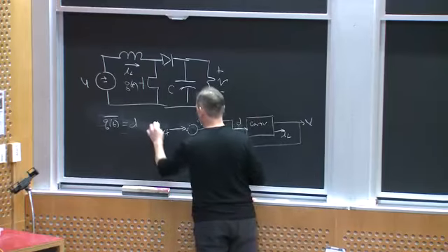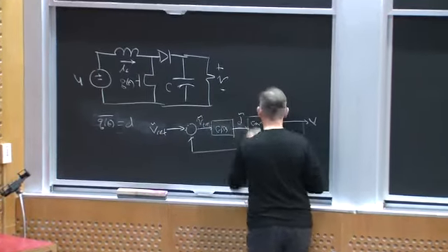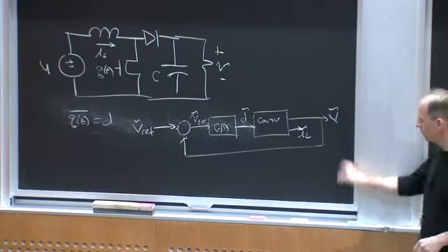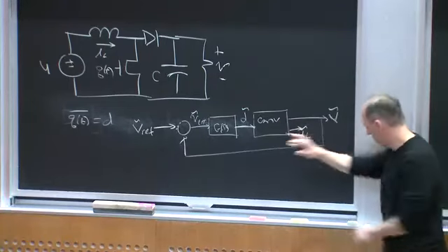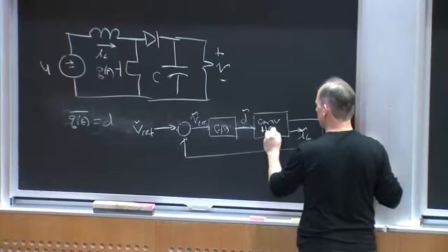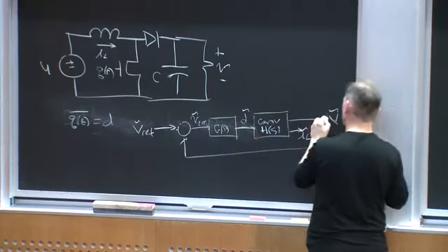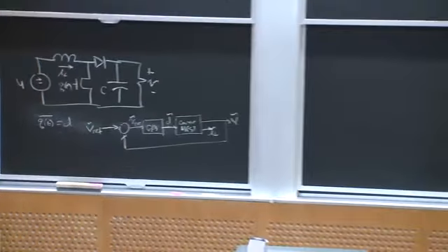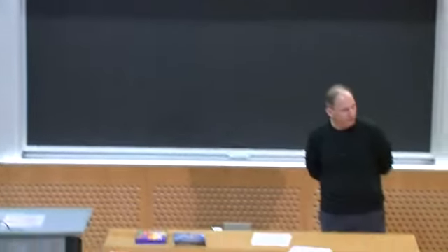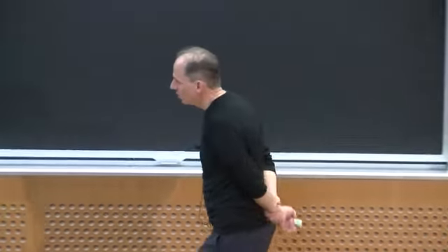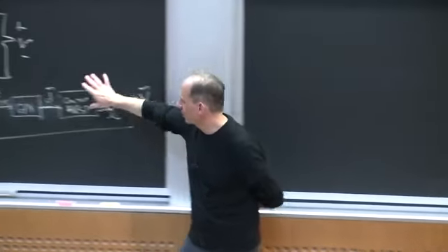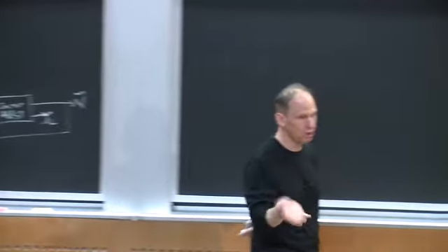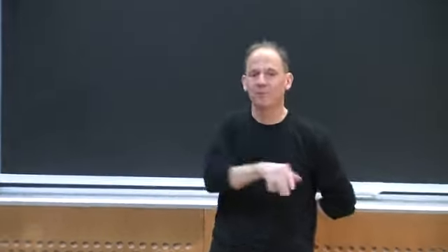So I might think about the variations in all these things to linearize it. And we came up with a model for our converter, H(s), which basically converts between variations in duty ratio to variations in output voltage, and we could design a converter. And when we did that, we saw a couple things. First, we saw that the dynamics were nonlinear. That's why we had to do this linearization. Now, are they always nonlinear in a converter? No. But many, many converters are.